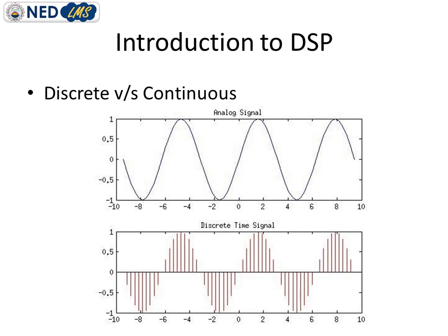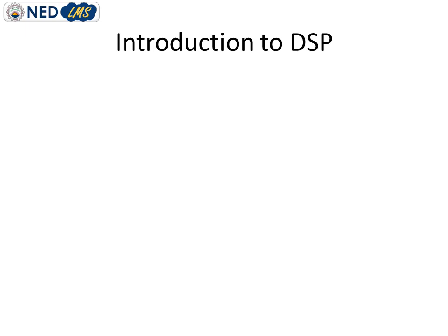In this slide we will discuss the major difference between an analog signal and digital signal. Analog signal is same as we saw in the previous slide, which is a continuous time signal, and if we convert the signal into discrete time signal, we have to take certain specific values of time and plot the function. Just you can see in the figure, the time axis is discretized and your function exists for specific values of time. So this is discrete time signal.